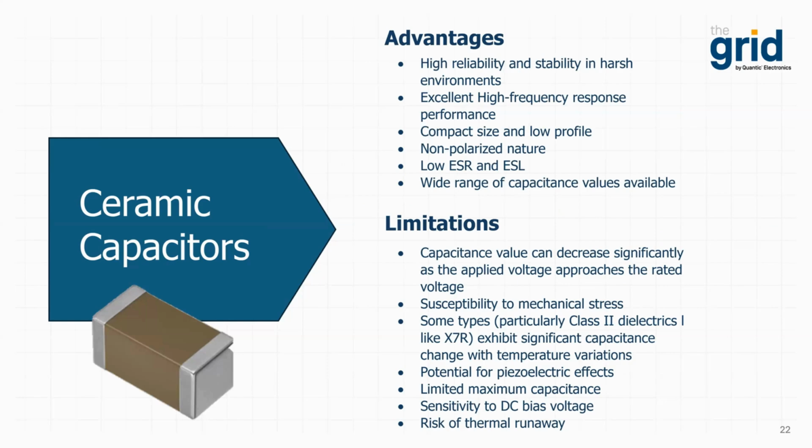In addition, excellent high frequency response, a compact size and low profile, and this is especially true for multi-layer ceramic capacitors, otherwise known as MLCCs. And this helps reduce the overall size and weight of the avionics equipment. They are non-polarized in nature, allowing them to be used in both AC and DC circuits. They're also known for having relatively low ESR or equivalent series resistance and ESL, equivalent series inductance. And they're offered in a very wide range of capacitance values from picofarads to microfarads.